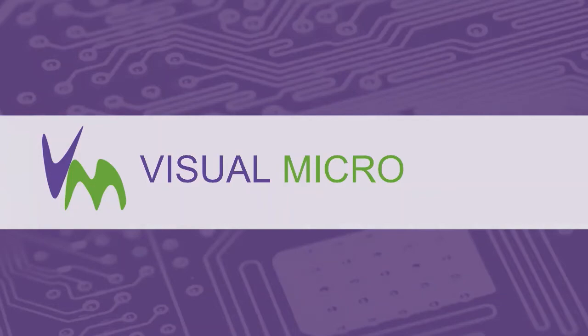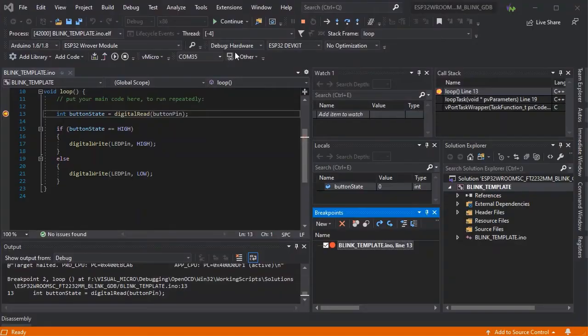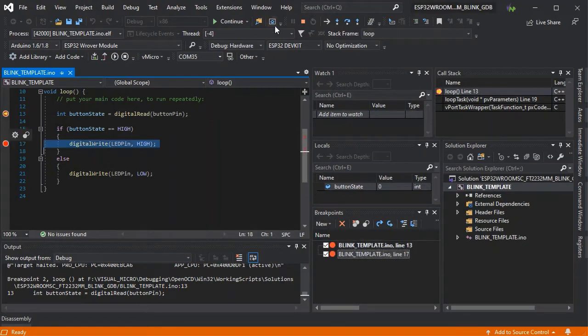So here we'll go through GDB and its speed at times. Here we can see a single breakpoint and it's executing very quickly round to that point. This is on the ESP32 and we're using the dev kit. So now with 2 it's still fast. Well, there we go, put it in the right place. So that's nice and quick, as you'd expect.